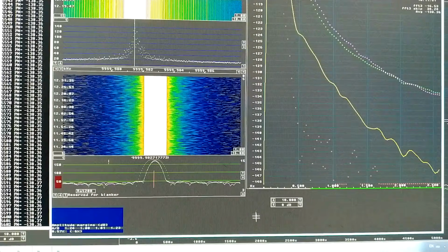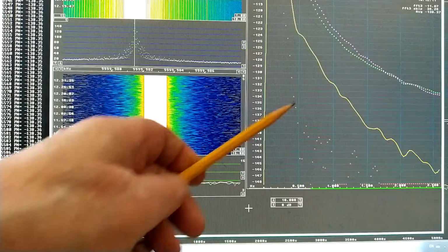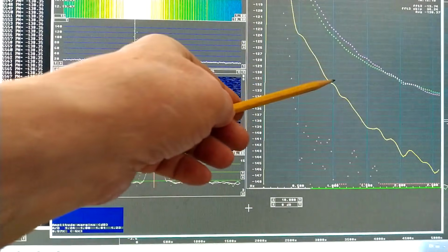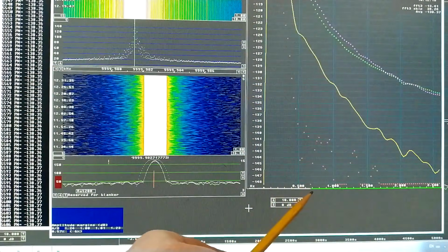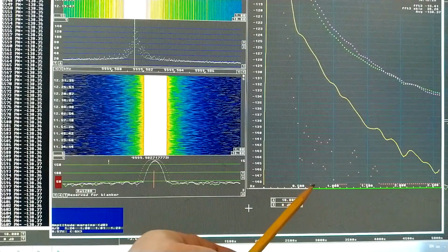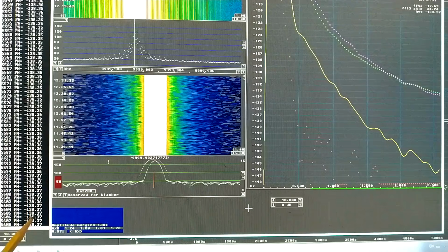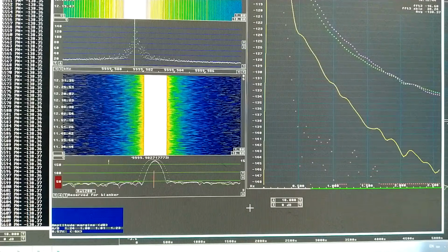It seems that temperature cycling the crystals has removed the noise problem. Now I see minus 132 dBc per Hertz in this instance of Linrad, which goes down to 0.8 Hertz. The average from 0.8 up to 2.6 is minus 138.37 after 5,600 averages. So this looks like expected.